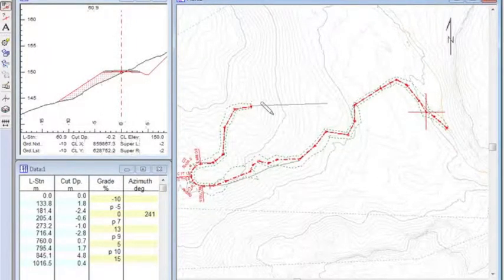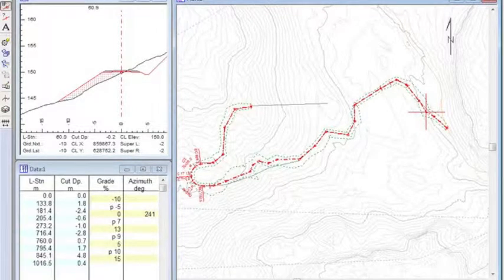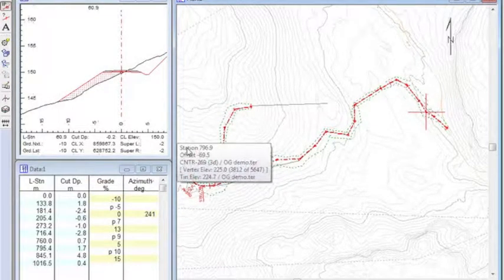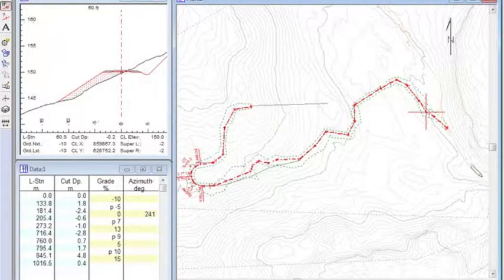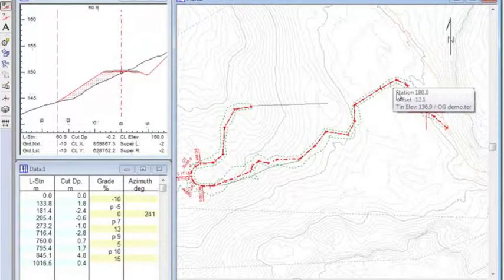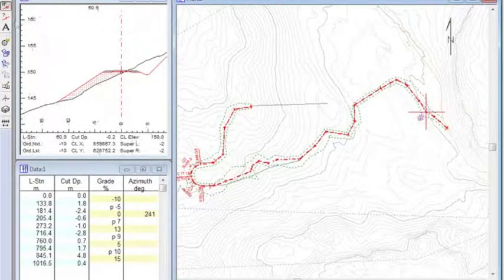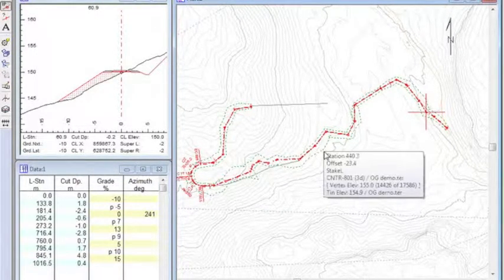So, you know, this is great for doing preliminary planning. You can probably lay out 90% of your roads, and then you go out and walk them and say, yeah, it's going to work. Some cases, you're going to go out and walk them and say, hey, wait a minute, this is a serious wetland here. We got a problem. Let's move the road somewhere else. Or this material that's sitting at 50% side hill is actually unstable, and we can't even do a full bench cut to cross it. It's going to be a problem. That's the kind of information you're going to get on the ground. But the LiDAR gives you everything else.